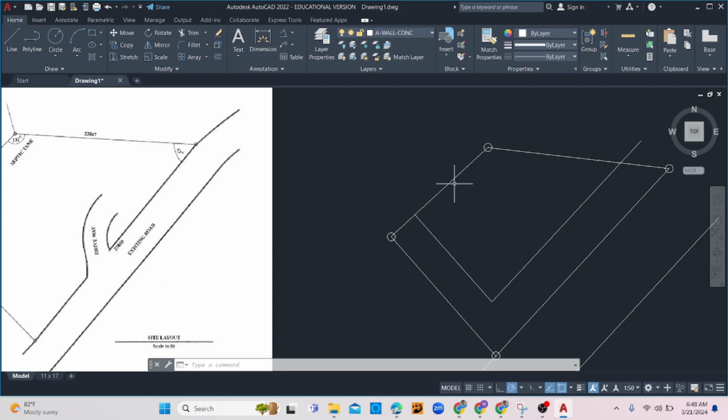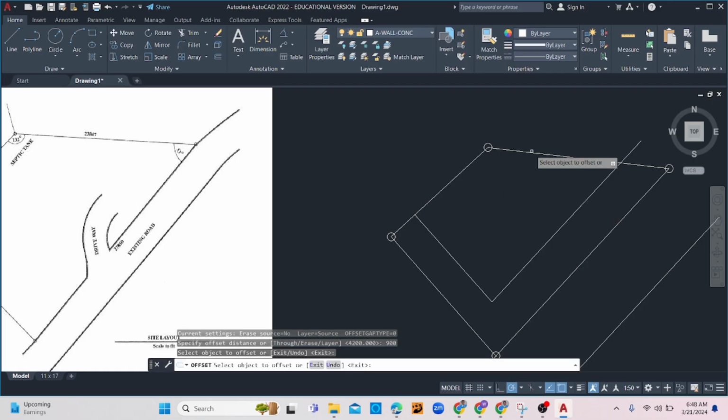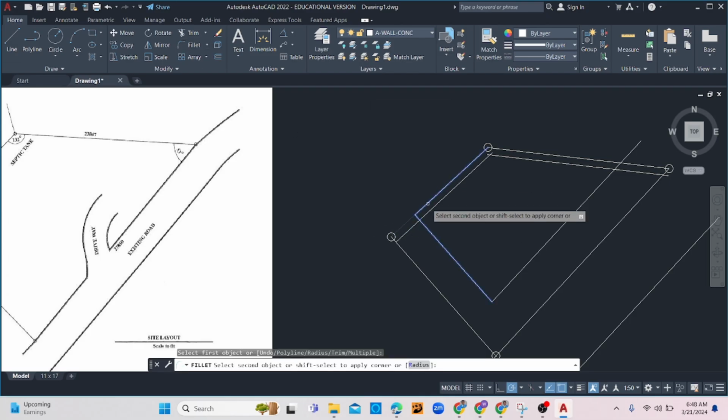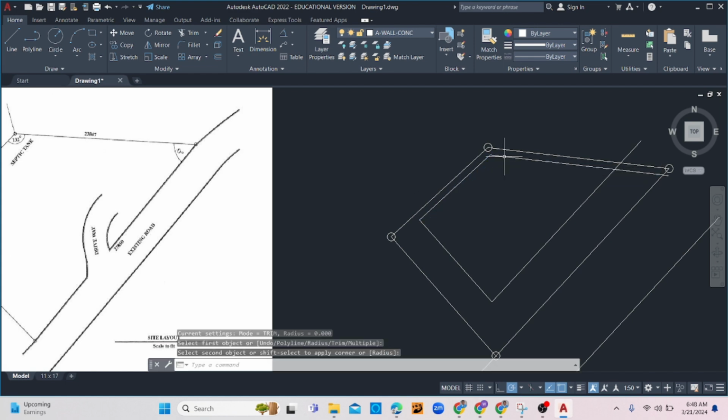We can add the setbacks or make up our own setback for the back portions of the property, and we can say it's 900, right? So let's just offset 900. Alright, and let's just fill out the corner. So our building is going to be within this space. We're not going to make our septic tank or any other property structures any closer than these points.